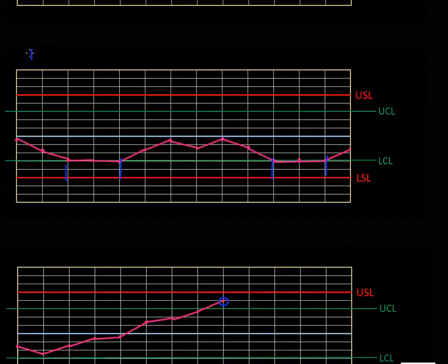And again, this is just experience speaking, but this could be truncated data, okay? Now, we already know in an SPC environment, when a process goes out of control, you investigate. Sometimes you shut down and investigate. It depends what your process is and what the rules of your shop are.